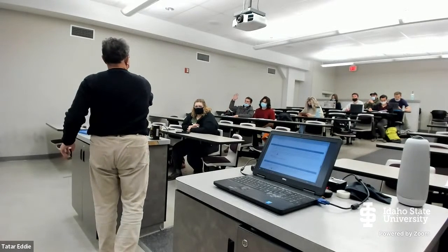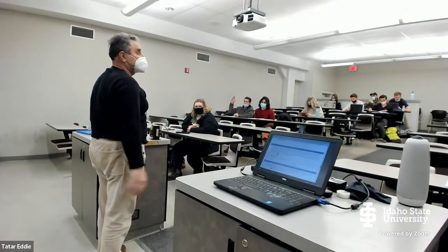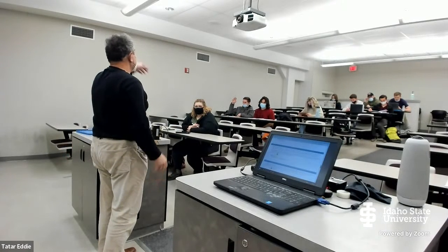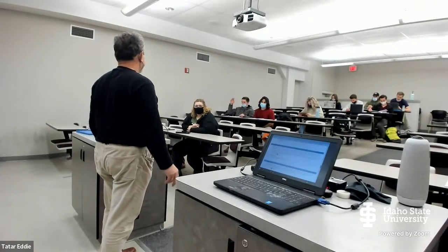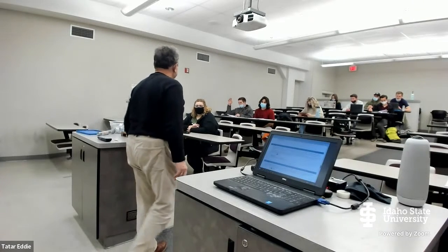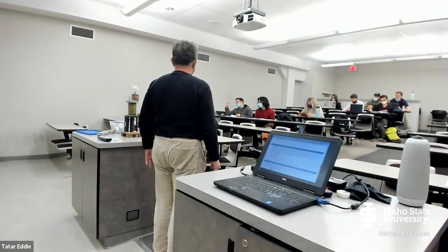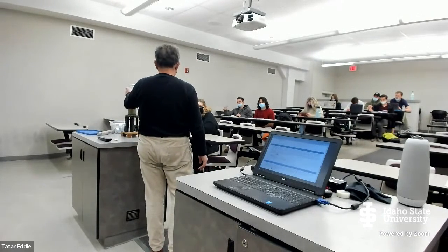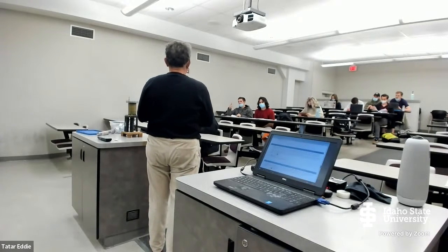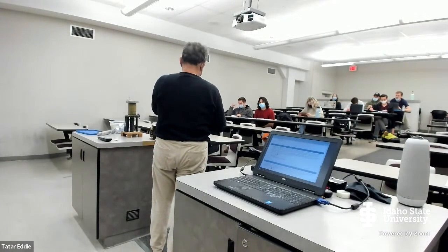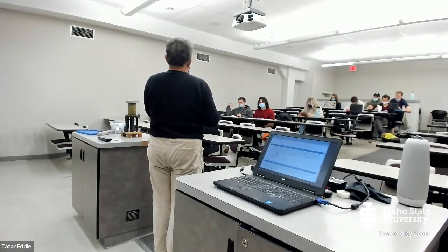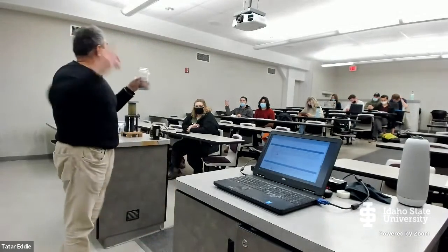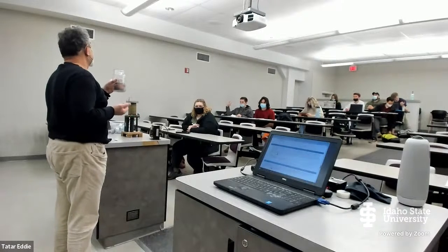You just put your cell phone on top of the charger, and instead of a light bulb, it charges some battery in your cell phone. So the variable magnetic field from the machine that you turn on creates variable magnetic flux here. Then that flux induces the voltage, and the voltage drives the current, of course.